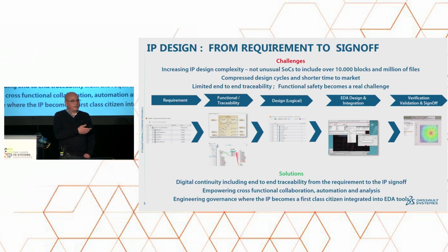This step is you do not have to focus on the logical behavior of your design, of your chip, but you have first to understand what is the functional behavior you would like the system to get. And here, by doing so, you are going to focus on the high-level behavior rather than on the implementation of the IPs.